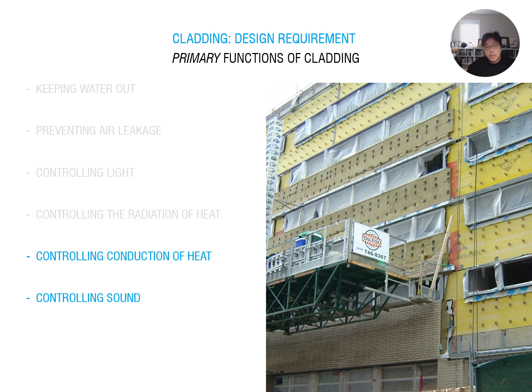Heat conduction is the heat movement between materials having different temperatures. When you protect against this kind of transfer, you have to provide insulation to resist the conduction of heat in and out of the building. Of course, you can also provide the vapor barrier too. And we also highly recommend using exterior resident insulation to balance temperature inside and outside and block this heat transfer between the inside and outside of the building.